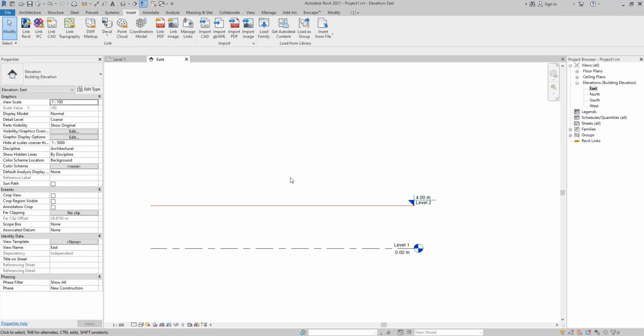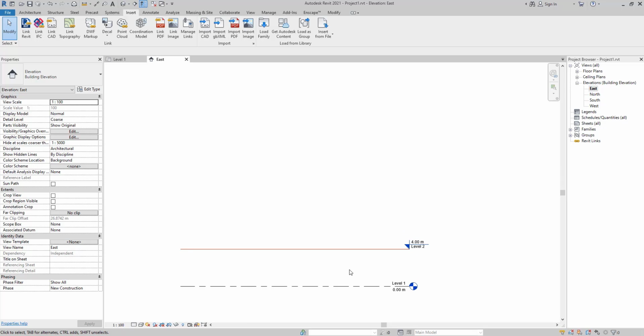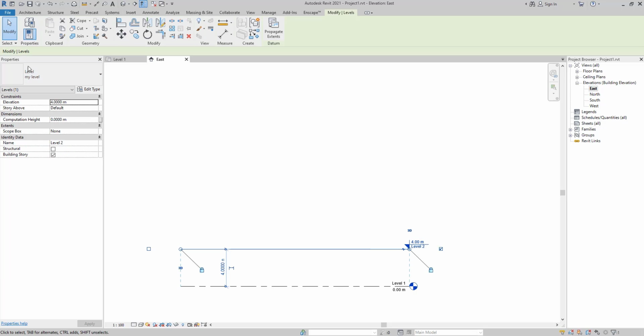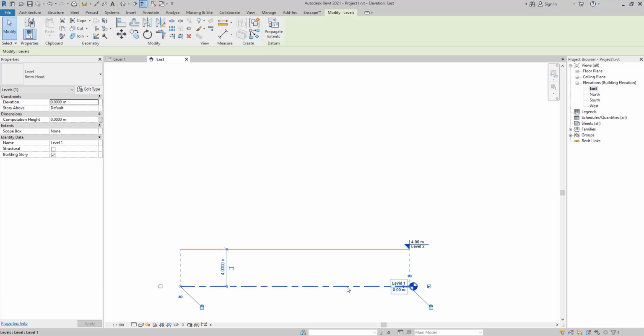The next step is how, for example, we are going to have 7 levels, and how we can have our own default levels which we created, this type of graphic, for the other levels. There are 2 ways. First, you create your first level and change the edit type, duplicate, and do the process.